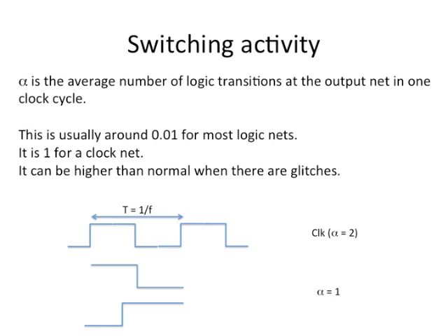So these are what are called hazards, dynamic hazards or glitches. That is not desirable, and eventually it will settle down to some value which you want to capture. So functionally the circuit might be okay, but from a power perspective it is bad because you are doing unnecessary switching, causing alpha to go up.